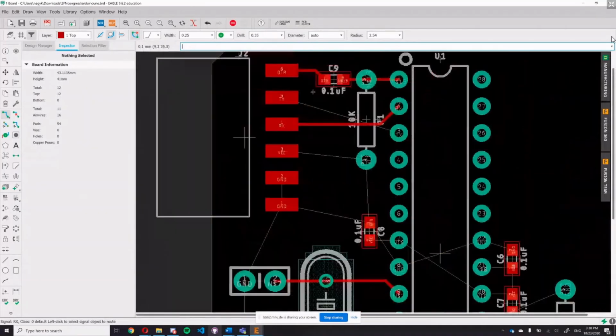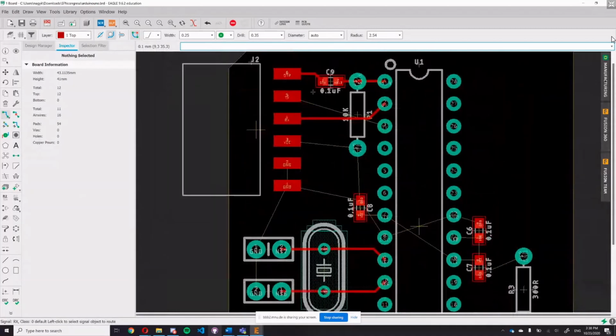I will first do the signal routes. Also, maybe many times I forgot, good practice is to do the power lines first, because they are higher priority. Normally when you're designing a board, you would go from the highest priority routes to the lowest. So you start with RF routes, for example when you have a GPS antenna, then you do the power routes, and lastly, you do the signal routes. But since this is a very simple PCB, we do not really need to do that.